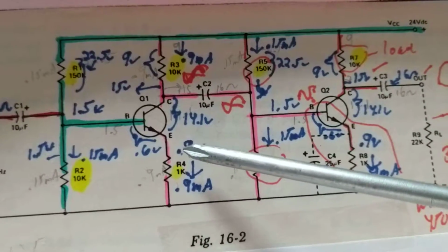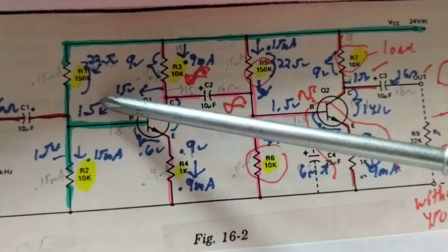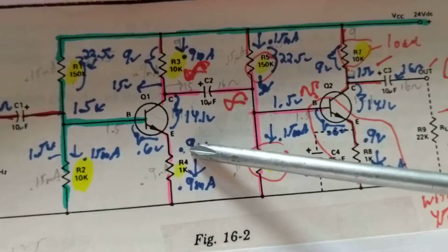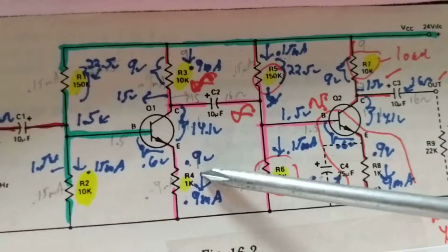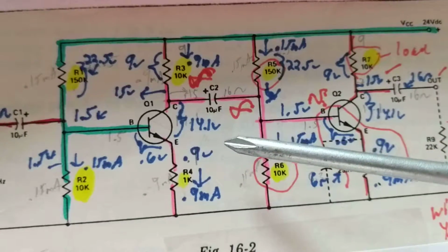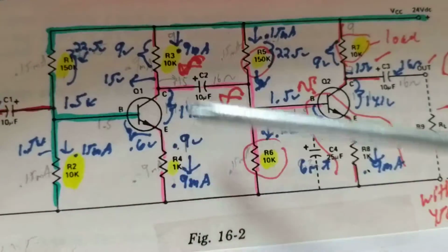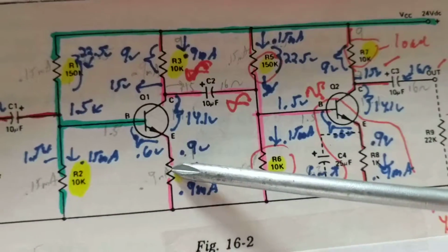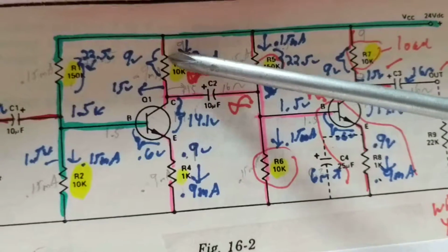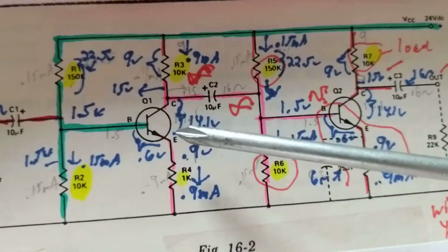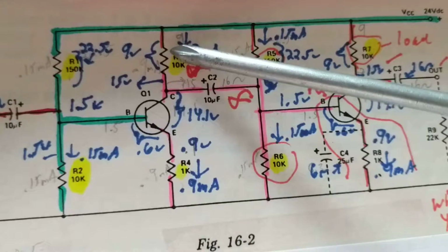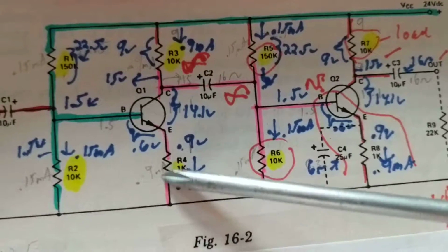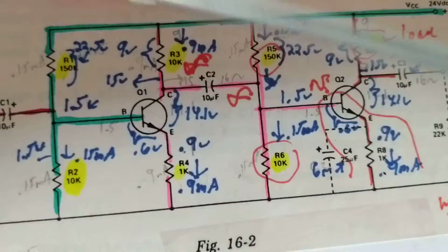And we figured that out because the key was, we knew how much this one was, we knew how much this one was, 0.6, we knew how much this one was left. That's the key. Now, this will give us many answers. So now, the key also is the base current is very small compared to the collector current. We also know that the combination of this collector current and the base current will equal the emitter current, the total, once they join together.